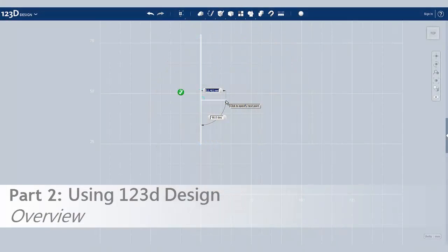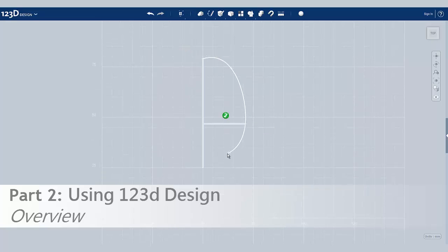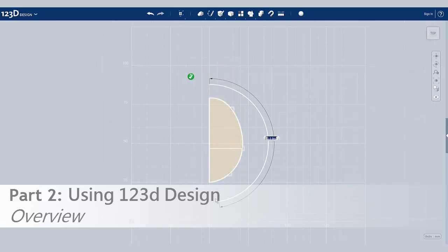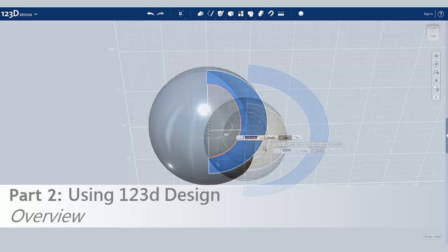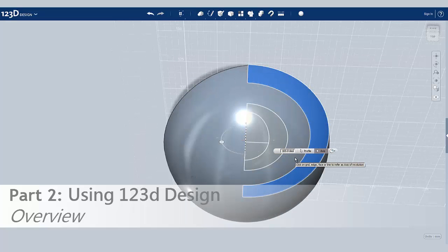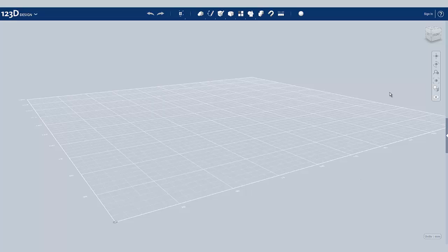The quickest and easiest way to construct this egg drop canister will be to sketch the side profile using the polyline tool for dimensions, and then using a spline tool to make the profile of an egg, and the 2-point arc tool to make the spherical cross sections. Then we'll use the revolve tool to rotate it about its center axis to make it 3D. Okay, let's get to it then.